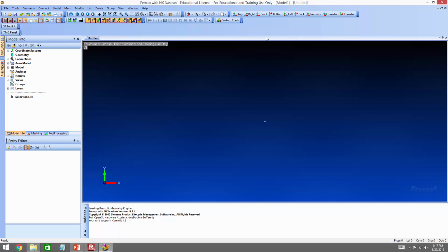Now, if you go to Geometry, you're going to see a number of things. You can create key points, like an object snap feature, for those of you familiar with AutoCAD or MicroStation. Basically, if you've got a bunch of important points in your model, create points and then you can snap to them. You can create one-dimensional objects, i.e. curves. You can do lines, arcs, circles, splines, and what have you.